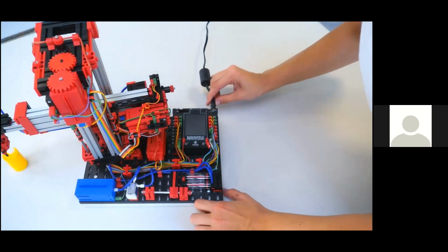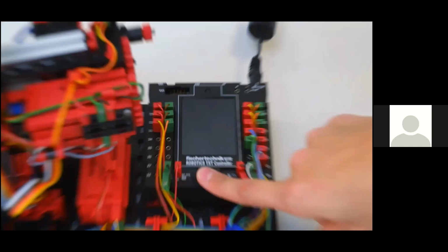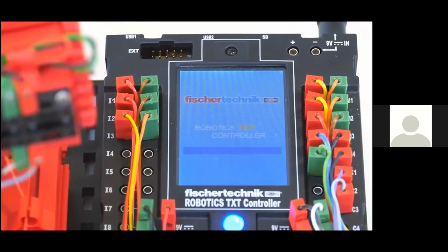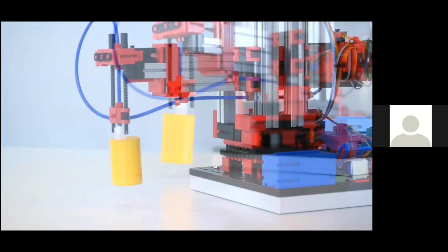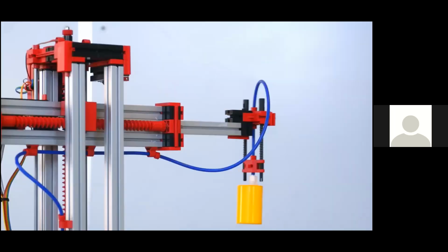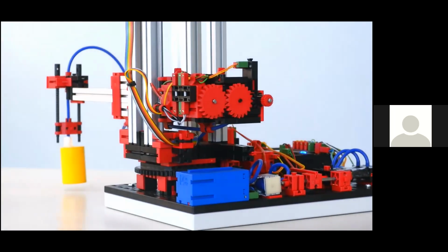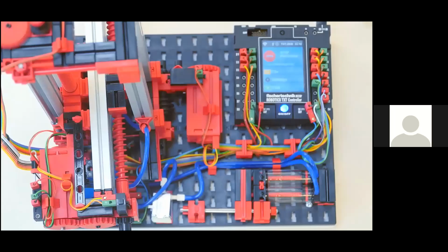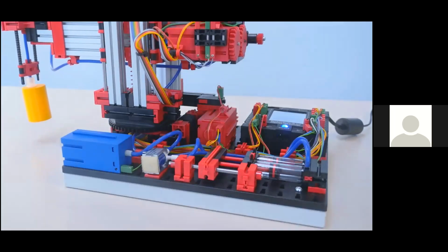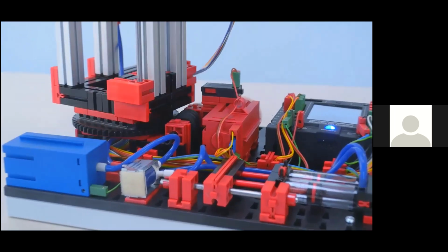The 24-volt versions of this model, as well as all of the first 5 24-volt models we will look at today, each have a relay board for motor polarity reversal and both a multi-pin connector, 34 pins with a grid of 2.54 millimeters, as well as additional PCB terminals with push-in connections for all inputs and outputs. Again, the 24-volt version of this model, as well as all 24-volt versions, will require you to provide the PLC